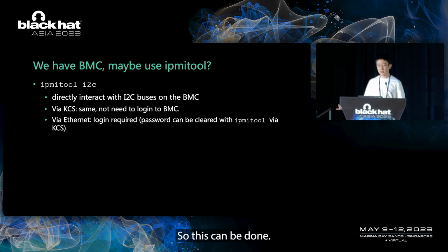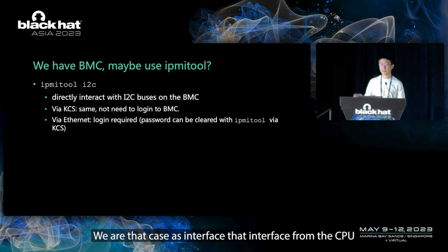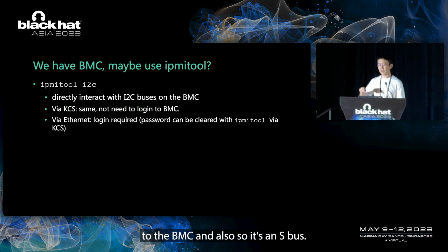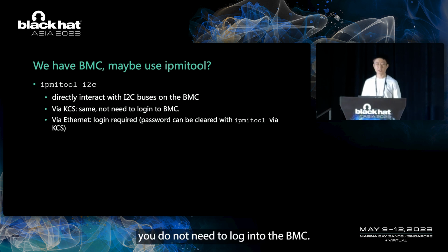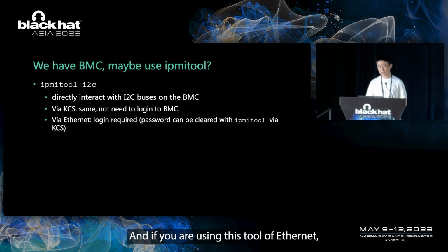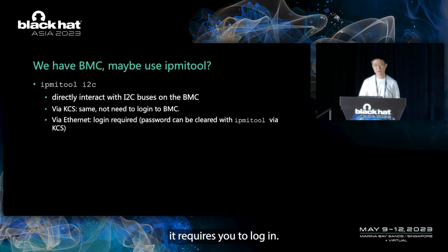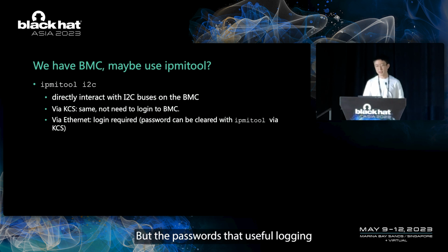This can be done via the KCS interface from the CPU to the BMC, and also through Ethernet. If you use this tool through the KCS interface, you do not need to log into the BMC. If you use it via Ethernet, it requires you to log in, but the password you use for login can be cleared with this ipmitool via KCS.